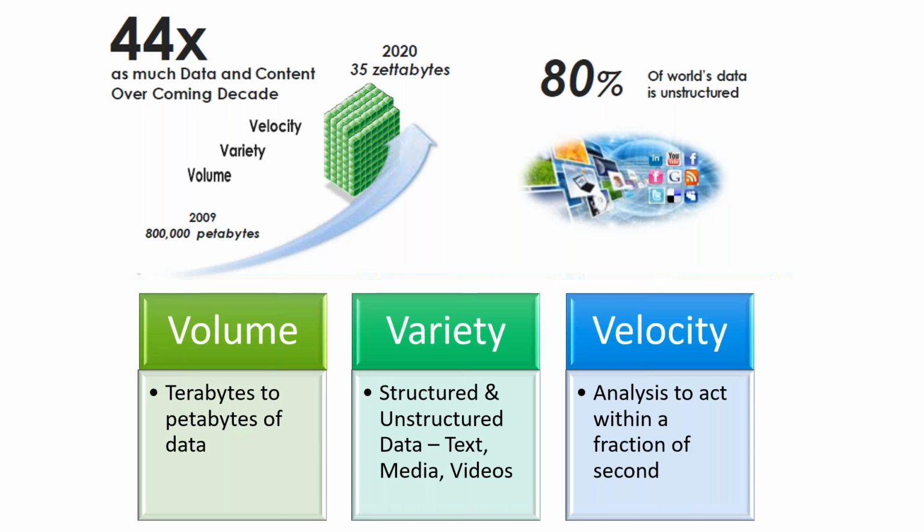That may take 1 or 2 seconds, or maybe 0.5 or 1 second. But in the manufacturing industry, we want to perform an action within a fraction of a second. So we want to do everything we do on the cloud, like processing, notifications, and analytics, on the edge level, meaning on the microcontroller itself. That's what we generally call edge computing.